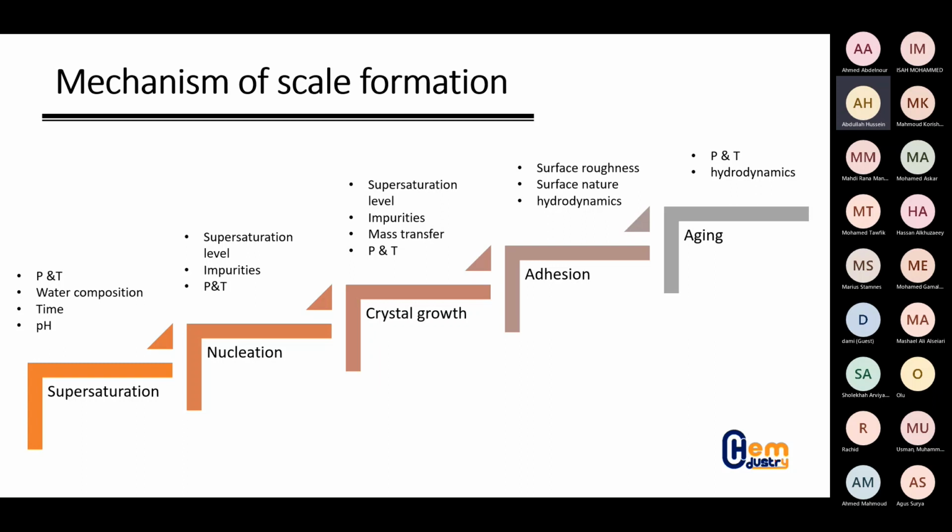And then, after time, aging comes. This is when the flowing fluid, with the effect of temperature and pressure, causes the deposit layer to gain some mechanical strength and harden, and it will be very hard to remove.